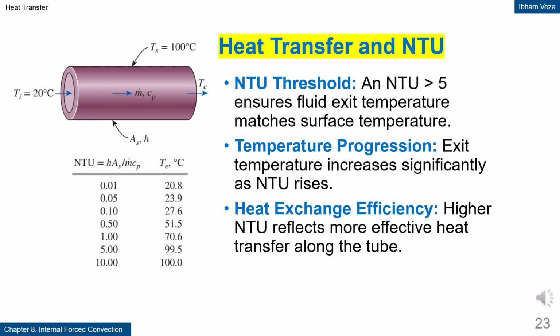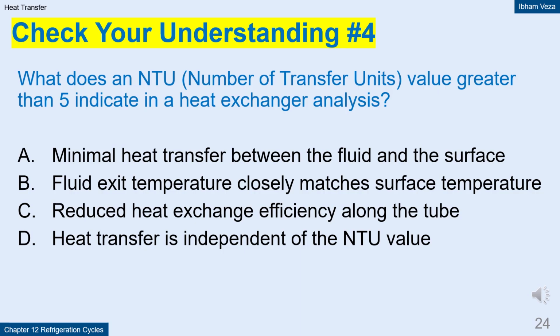The larger the NTU, the more effective the heat transfer process becomes. This can be achieved by increasing the surface area or the heat transfer coefficient. This concept is very important in heat exchanger design. Correct answer, B. Fluid exit temperature closely matches the surface temperature.